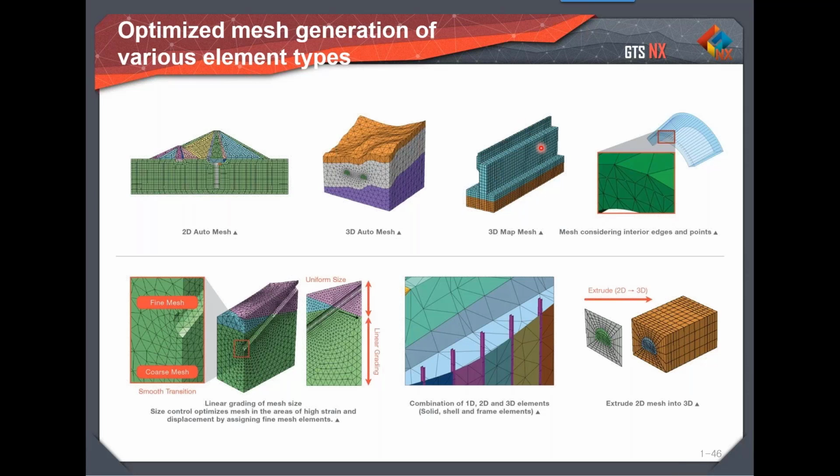As I said initially, we have an option for auto connect to connect your solids with adjacent solids. When you do that, the software can differentiate the length and dimensions of each solid separately. Because of that, while meshing you will find a fine mesh in one place and a coarser mesh at the boundary. That means the transition from coarser mesh to finer mesh is automatically considered. There is no need to provide seedings and so on. The software will automatically adapt the mesh size.